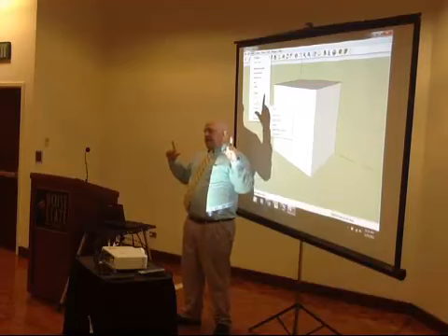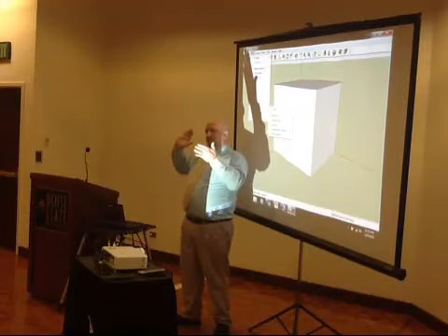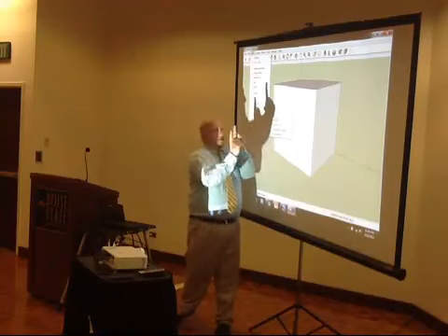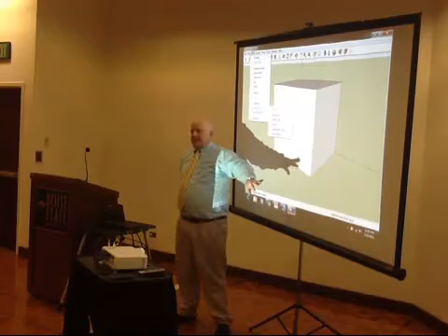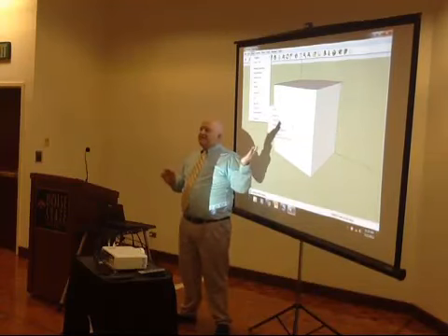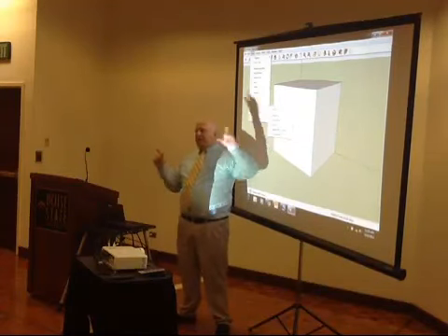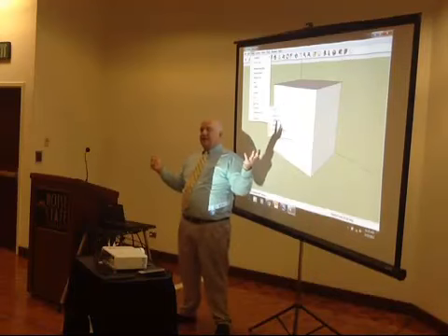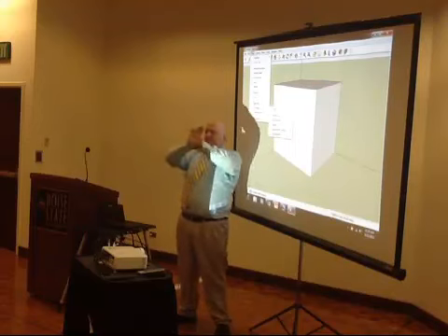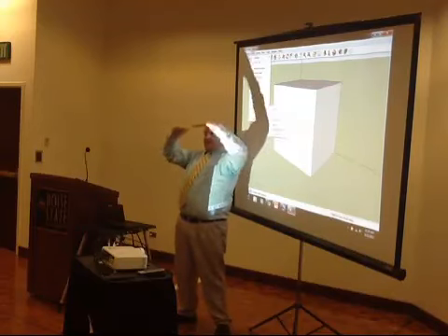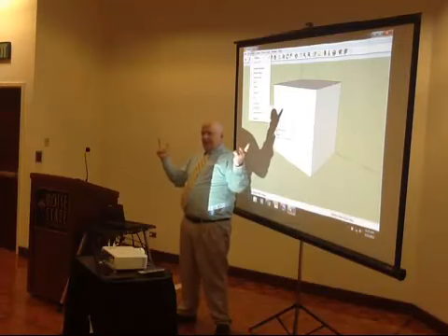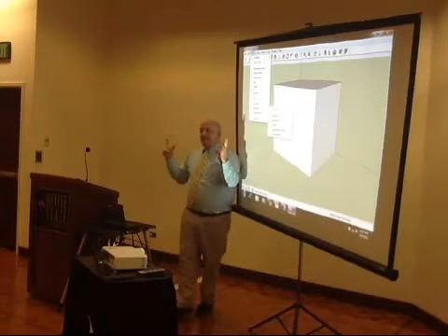It's just a gray surface. But it's possible within Google SketchUp to say, use this picture as the face of this shape. And so one of the easiest things to do in making buildings, the way that Google SketchUp creates buildings, is you create a simple shape, take a picture of it, and splash it across the top of the front of it, modify your shape until it matches up, and then you've got a simple primitive of your building.